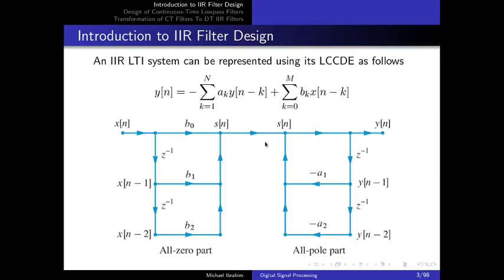And this is a signal flow graph of an IIR system, and as you can see, the input x of n is applied to the system, multiplied by constant b0, and then delayed, multiplied by b1, another delay multiplied by b2, and this part corresponds to the feed-forward part. Whereas this part of the filter corresponds to the feedback part, where the output y of n is fed back into the system and multiplied by a constant, and then another delay multiplied by a constant. Add all of these and it will give you the feedback part of the equation.